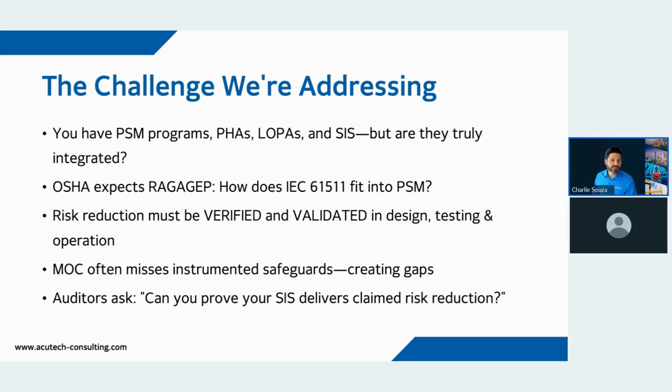So how does that fit in PSM? Risk reduction must be verified and validated. Like I said, after the HAZOP and LOPA has dictated how much risk reduction is required, someone must verify and validate that during design, testing, and operation. And that would be, let's think of it as a safety function, right?